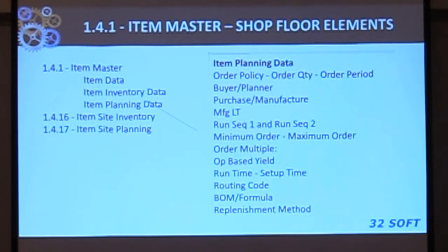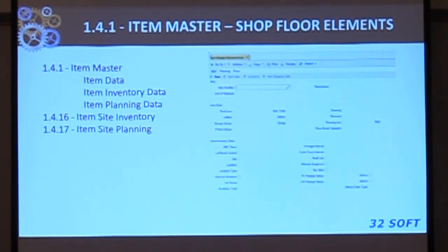And the system will use the BOM code equal to your part number if you don't define an alternate, or you can define your routing codes, we'll talk about in just a second. And then when you cut a manufacturing work order, you can either use those defaults of routings in BOMs, or you can go ahead and use an alternate that you have defined.